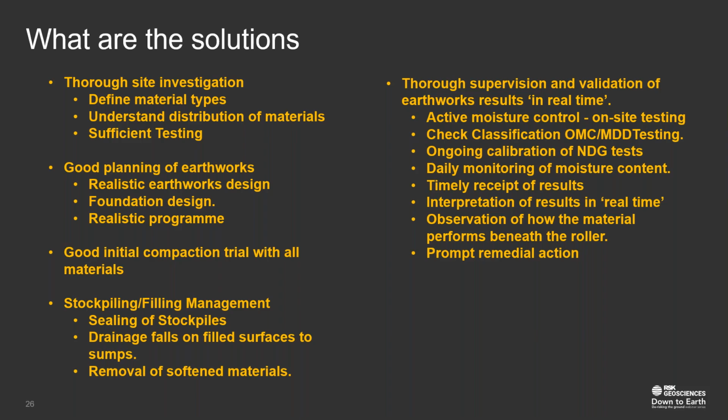But we also need to have thorough supervision, either internally, if a contractor, or if you've got independent supervision, such as ourselves on site, looking at the works, actively managing the moisture on site, undertaking tests on the moisture content to make sure that the material is going down at the right moisture content, keeping on top of and checking the classification is what it should be, making sure that everything is properly calibrated, and monitoring the results, and very importantly, interpreting the results in real time.